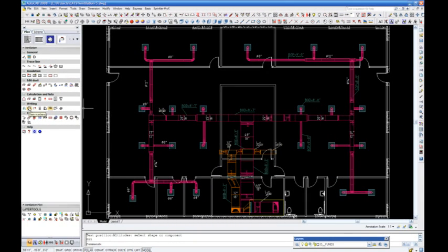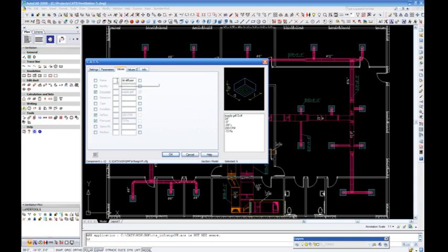In the C.A.T.S Commander, item tags may be selected to differentiate between various components within the system, such as flex duct, diffusers, and all other components. Here we select a diffuser, indicating the type of diffuser and the CFM.